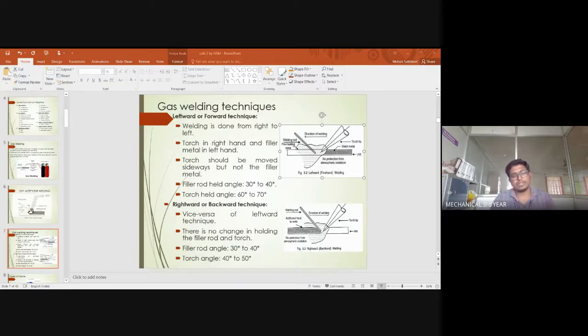Since we have seen this in all the previous topics that we have covered in this particular session, we are talking about flux coating. So why is flux coating used? In order to reduce the atmospheric interaction. Shielding gas is also a similar thing. In order to reduce the atmospheric reaction, you can use either flux or shielding gas. So let us see what fluxes are being used: lime, silica, calcium fluoride, and magnesium oxide. These are the various types of flux used here.